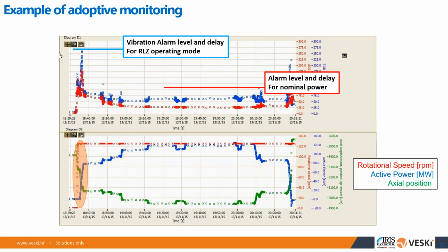Is it self-excited, which comes from hydraulic parameters of turbine design, or a function of magnetic parameters? I mean the source of it. The self-excitation is turbine related, not generator related. It comes from the fact that the energy has nowhere to go, in a way. The potential energy of water has to be turned into kinetic energy, basically to power the turbine, and then that probably doesn't happen.